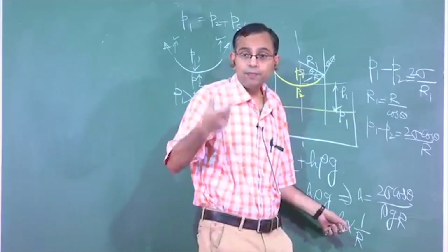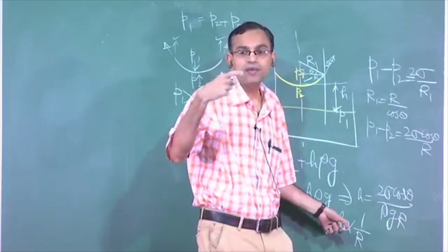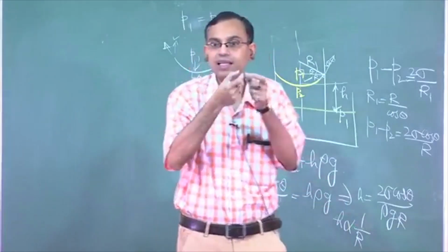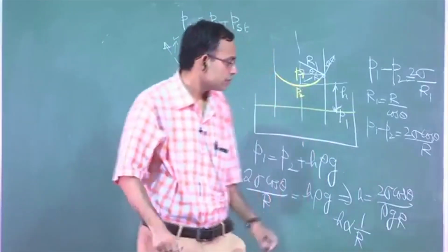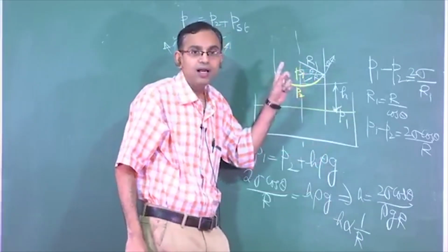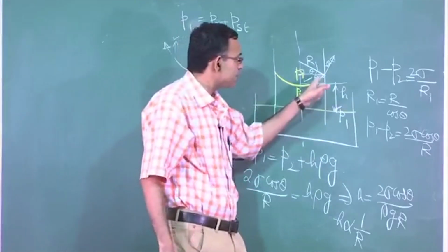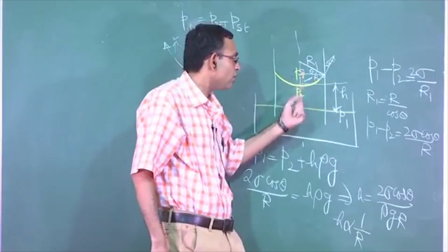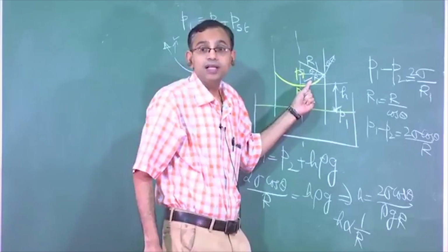So in a pipe there is surface tension, but that is not manifested as an effective force to drive the flow, but in a narrow capillary that can be an effective force to make the fluid move from one height to the other. So this capillary rise is important as a formula, but it is also important to understand that this is just the description of statics. How fast or how quickly this capillary is being filled is called capillary filling dynamics.